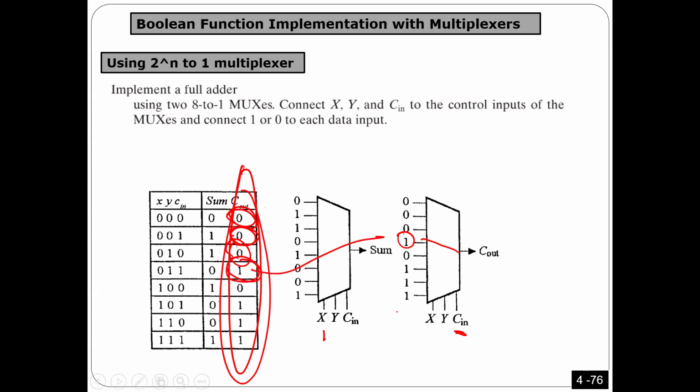Is that okay? So again, what I'm explaining here is, I explained what is multiplexer. For sure I will continue teaching this part, but here what I'm teaching is, if you want to use a multiplexer to implement a function similar to what I did in the decoder, this is a naive way to do it, or a simple way to do it. I'm just gonna put here the value of the function. I know when the input here is equal to number 6, the output will be connected to number 6. So whatever you want here, what the function is telling you, the function is 0 or 1, you can just put 0 or 1.